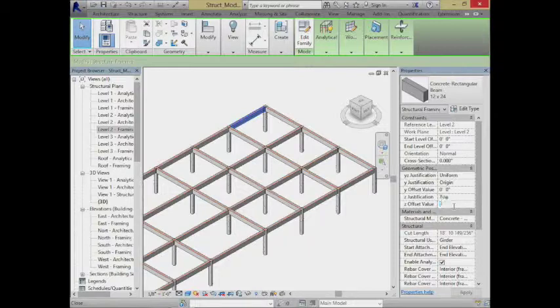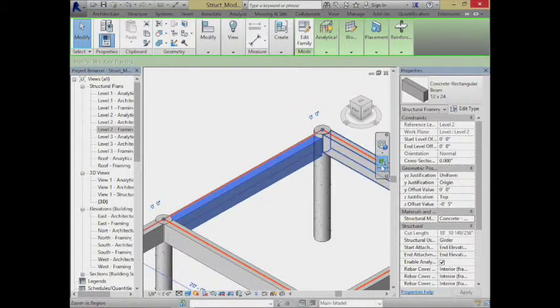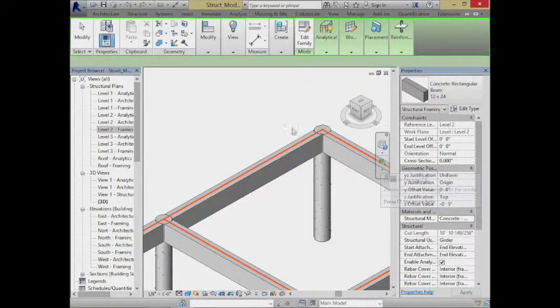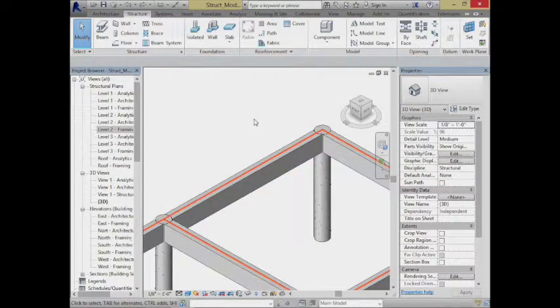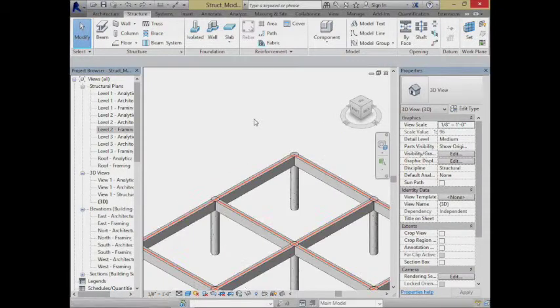I just have to give it a little bit of offset, whatever it takes to lower it down so that it'll be beneath the slab. But again, since it's concrete, I'm not going to worry about that now. That's really one of the few differences between thinking about modeling steel and modeling concrete. It's just allowing that steel doesn't have the ability to magically merge. You need to go through and be very explicit about its locations.